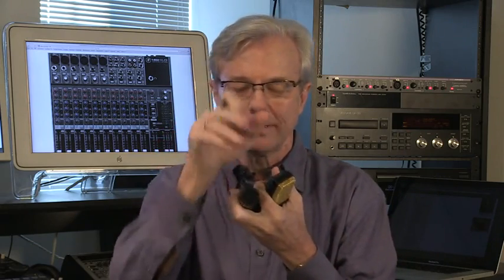What those do, they narrow the energy field more as you get in front of the microphone, and usually the hyper and supercardioids will allow some energy directly behind to come into that. So those would be for particular applications where you don't want exclusive sound coming in, but also you want some of the resonance of the sound bouncing off the back wall or some of the ambience of the room sound to come into the microphone. So depending on what you're recording or your sound application, you would choose one of those cardioid patterns. So in order to have a versatile microphone, and the more expensive microphones will give you this shifting.